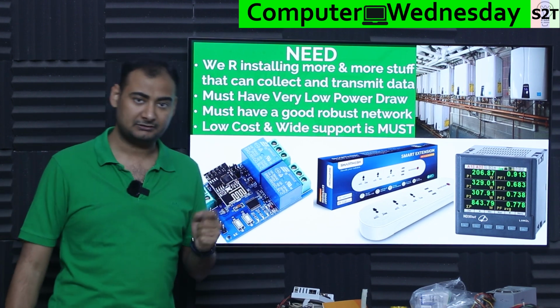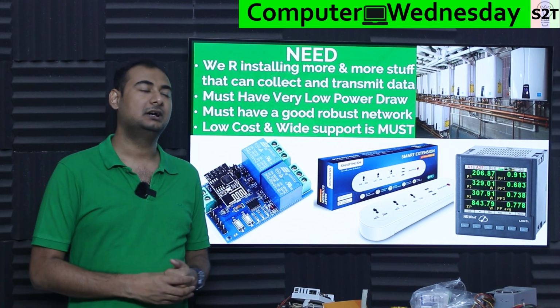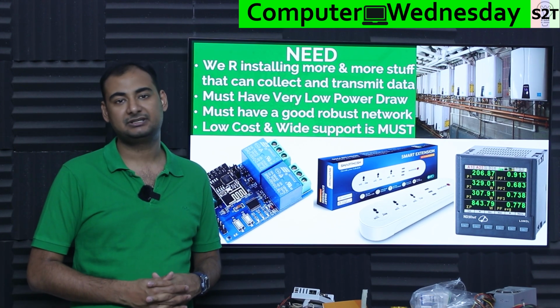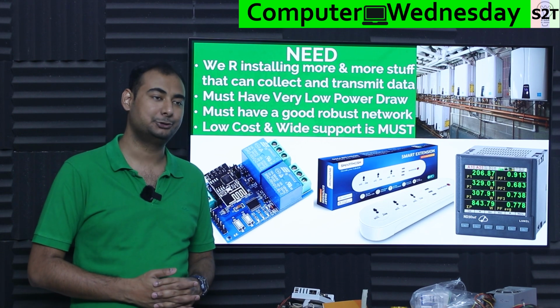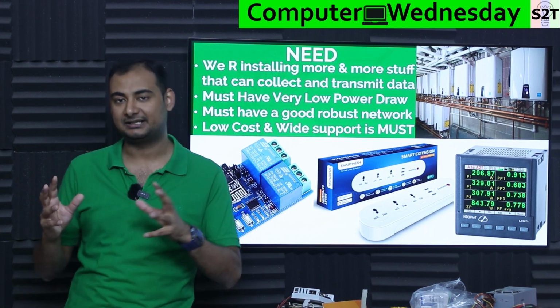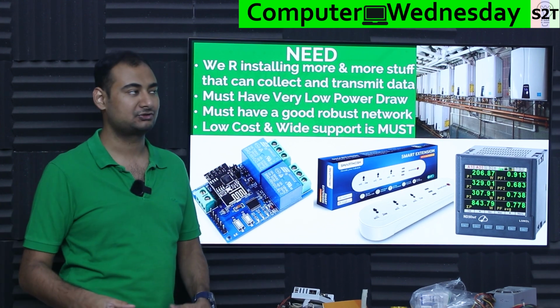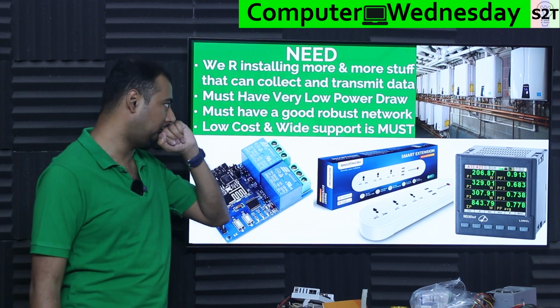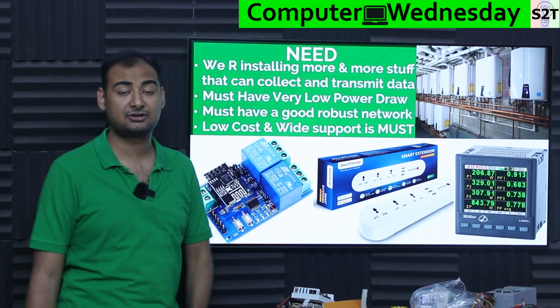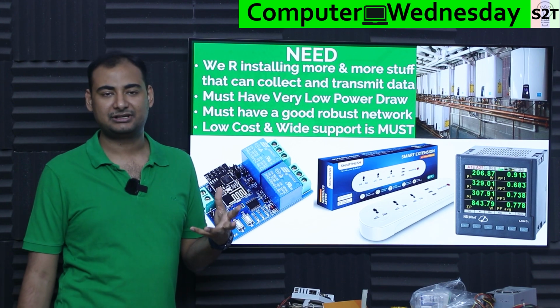It must have very low power because we cannot use wire here, as it would become a wire mess, and it would be way too expensive and way too uncomfortable to do physically. So we have to be wireless, but it also has to be battery powered, so it's small and easy to conceal. Conceal as in, just put it and forget it. It should not be like a mobile tower everywhere. So low power draw is compulsory, and low power draw is also required in some other ways.